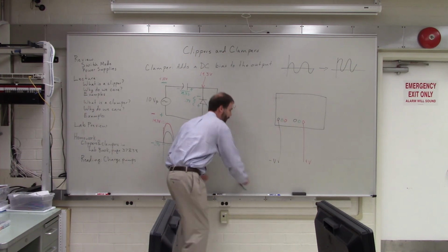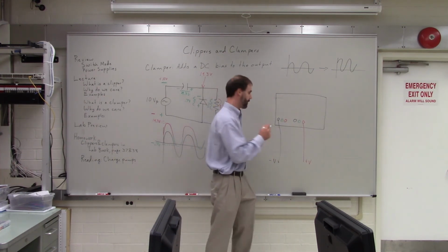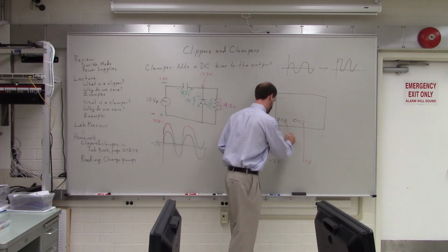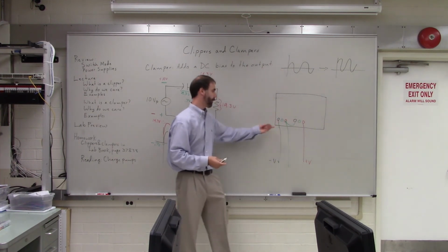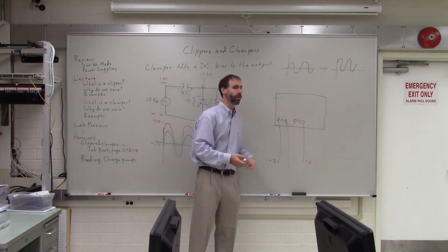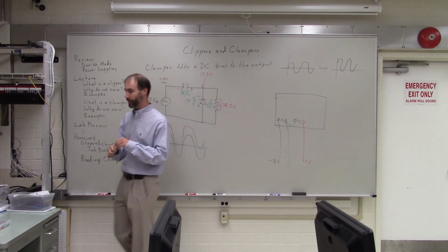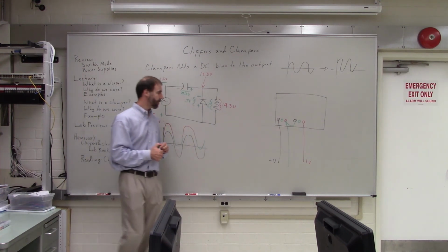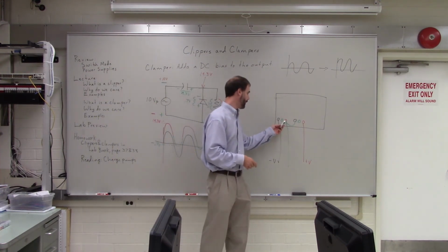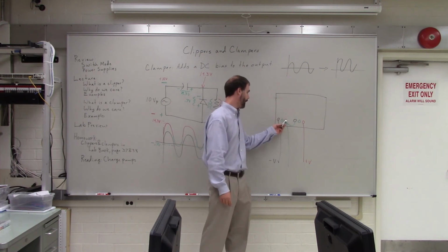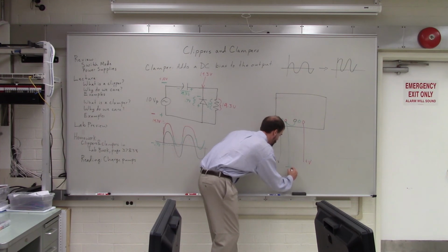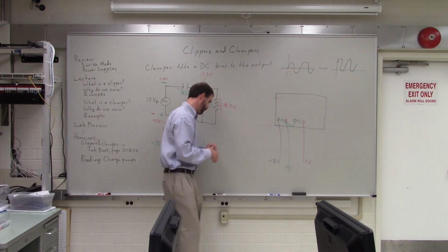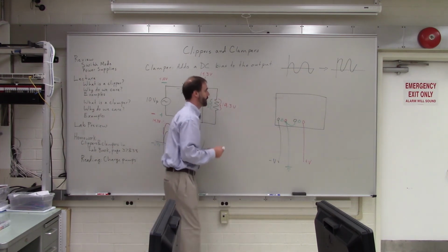And then the green cord has 2 prongs on it. So the green cord, one prong goes in there, the other prong loops across to there, okay? Now everybody sees the green cord and they think it should go in the green holes. I know I did that the first time I looked it up. But that's not the way that it works. You put the green cord in the red hole and the black hole. And then this becomes ground. Yeah, exactly. It's two power supplies in series.